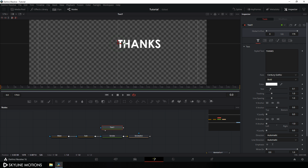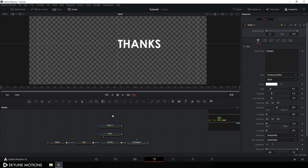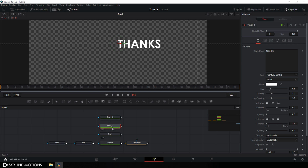And I'm going to animate 3 different lines over here with different timing. So we have to take 3 different text node over here. So select this text 1, hit Ctrl C to copy, hit Ctrl V to paste, hit Ctrl V again to paste, and let's rename it properly. So hit F2 on the keyboard to rename, and let's call it text 2. Select this one, hit F2, call it text 3.